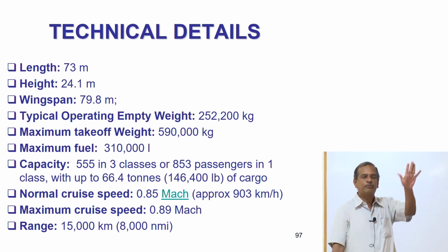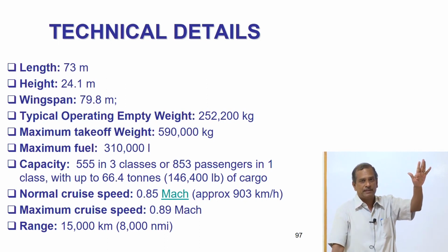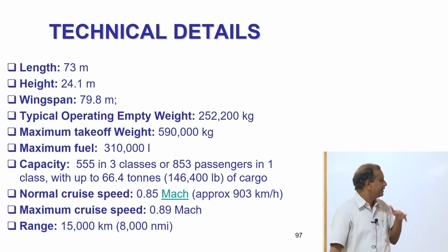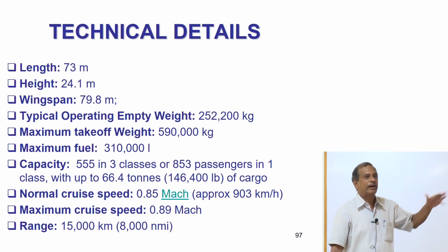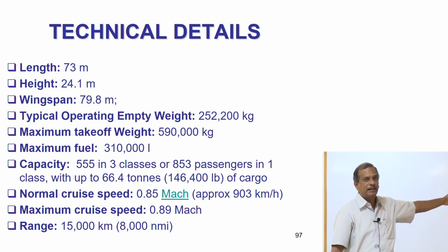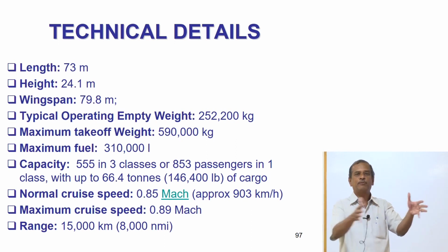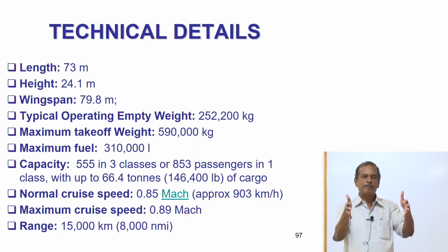The aircraft takeoff weight is more because its fuel is full. The landing weight is less. So the challenge before you is, how do I design a sustainable pavement for a load of 590 tons? So unlike a highway where the traffic wanders, in the case of a runway pavement, they follow a particular path. So wheel rutting will be along a particular path.